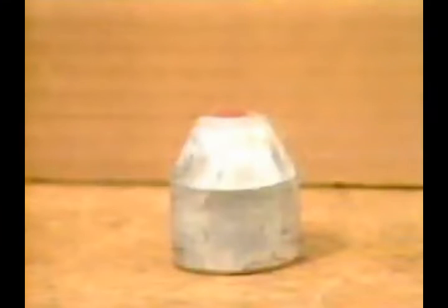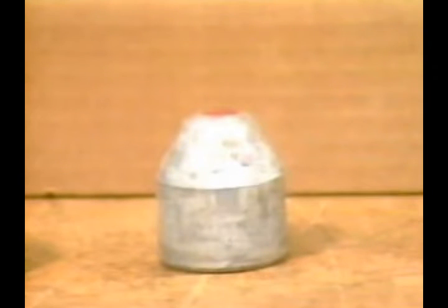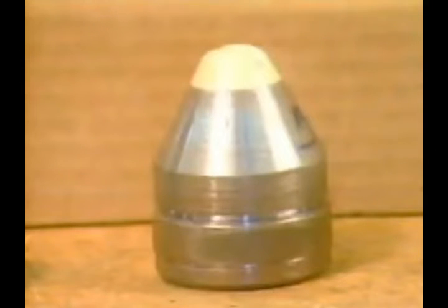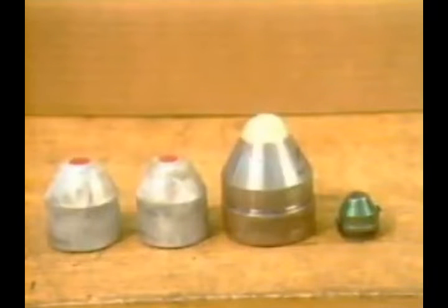For example, although the exterior of these charges look identical, this charge is designed to give large diameter perforations for easy gravel packing, while this charge is designed to penetrate deeply with a somewhat smaller entrance hole. Here we see a charge that is designed to be run in a 6-inch or 7 1/4-inch diameter carrier, while this charge is made for a 1 11/16-inch carrier. There is quite a bit less explosive power in this smaller charge, but that power can still be focused on maximizing hole size or penetration, depending on the needs of the completion.